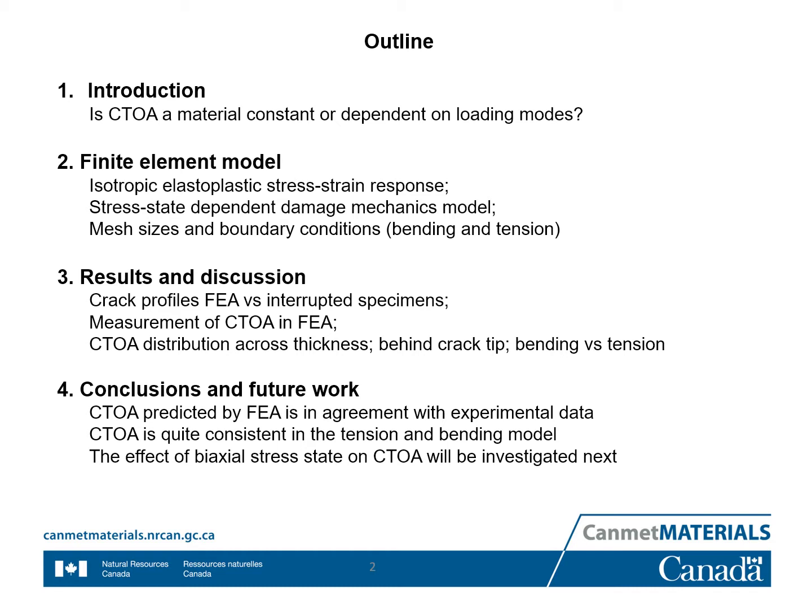And then we will discuss the measurement of CTOA in simulations. And then we will discuss the CTOA distribution across thickness at various distances behind the crack tip, comparing the bending mode and the tension mode. And in section 4, we will have conclusions and future work. In this research, we find that the CTOA predicted by FEA is actually in agreement with experimental data, and the CTOA is quite consistent in the tension and bending mode.